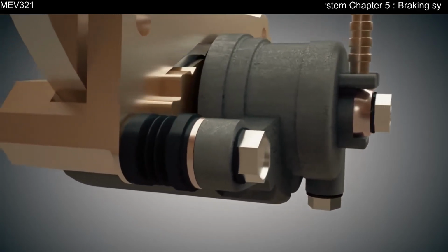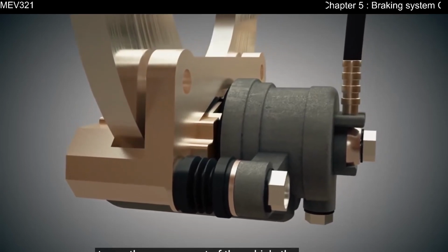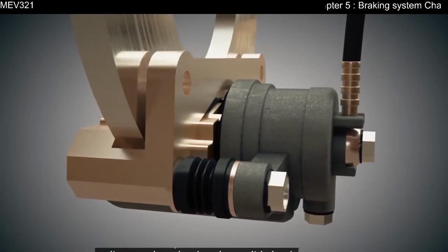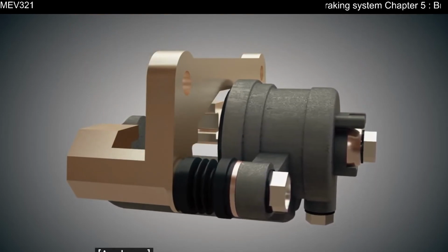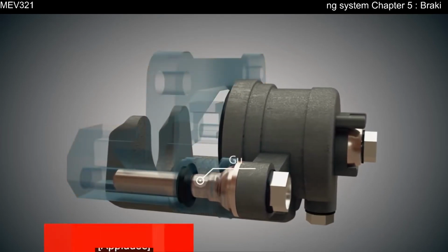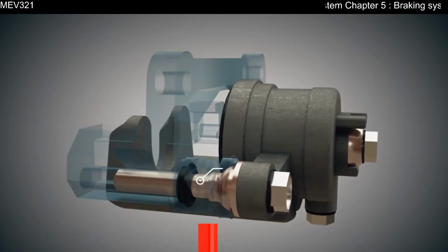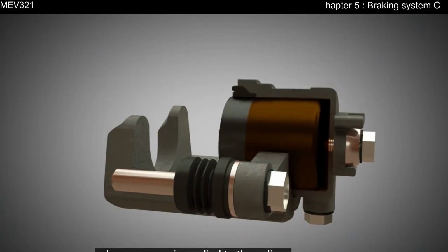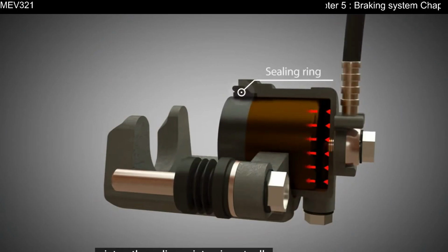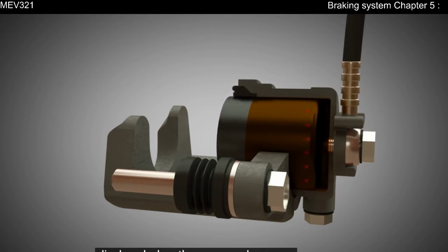The brake carrier is rigidly connected to another component of the vehicle. The caliper, on the other hand, can slide back and forth. Two guide pins on the caliper serve this purpose. When pressure is applied, the caliper piston is axially displaced. When the pressure decreases, the caliper piston returns to its initial position.